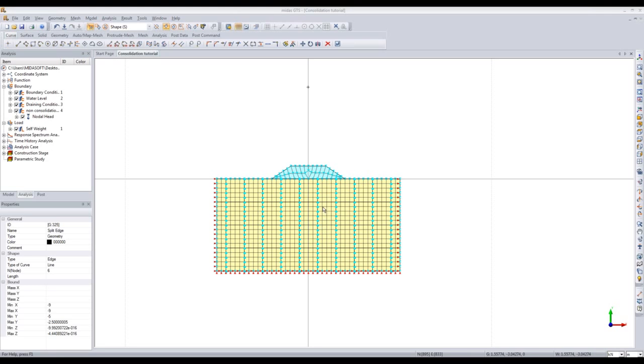Okay. So the thing is, once you choose your boundary conditions, you have your mesh set here. Once you select the entire mesh set or the entire perimeter, the program will recognize everything that's enclosed within the perimeter itself. So anything inside the perimeter will be fully saturated as well, because you didn't just choose the perimeter, you chose the mesh set.